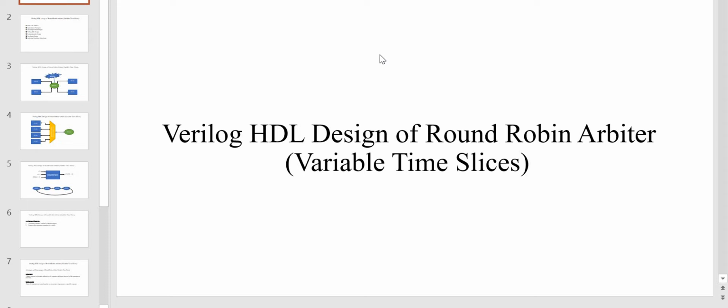In this video, we are going to study another type of round robin arbiter. As you remember, in the previous video, we studied the fixed time slice round robin arbiter, where the time allocated to every requester to access a shared resource is fixed. For example, let's say that every requester is able to access the shared resource for 4 clock cycles.